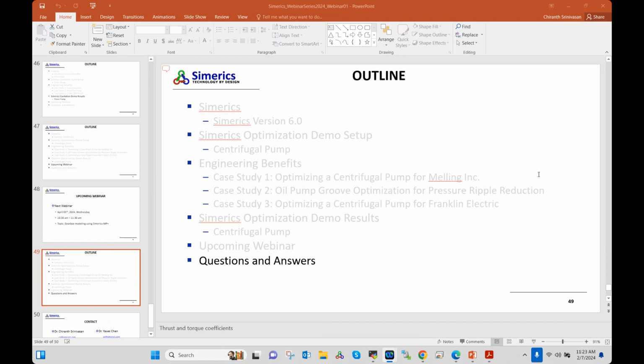From Sheetal Jain, in the constant gas mass fraction model, is the gas or air always free, or does it dissolve into liquid as pressure increases? It's always free air, and it will reduce and go into liquid. It will not become dissolved, but it just becomes liquid as the pressure increases. So there is only free air in the constant gas mass fraction model.